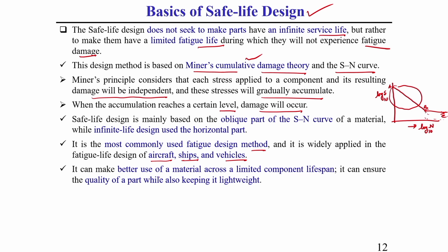It can make better use of material across a limited component lifespan. That means it can make a component lightweight for its lifespan. What I mean is, it maintains the quality of the part as well as the light weight of the structure, which is generally a requirement of this modern age, of modern technologies, that it can fulfill. That is why this basic safe life design technique has wide application in the field of fatigue design.